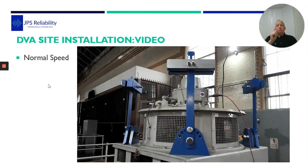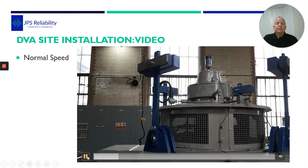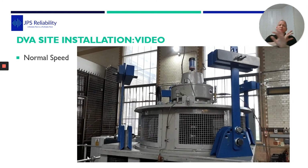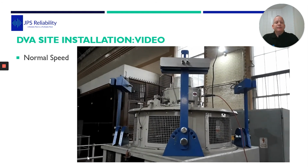Now they're only good for one frequency. And on this unit, it ran at set point 3 the most, so we tuned it to set point 3 because this is the one they're running at 24/7, which is causing the fatigue. So as you see here now, at set point 3, they're exciting, and we were going around adjusting them, tweaking them, and they were all sort of interacting with each other, but they seem to be working.